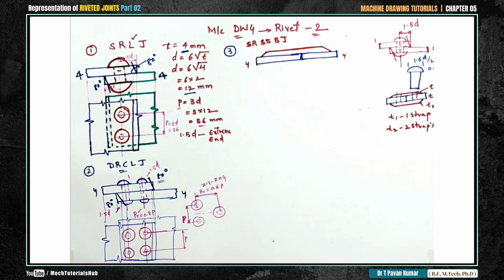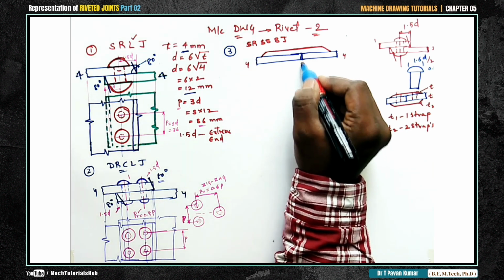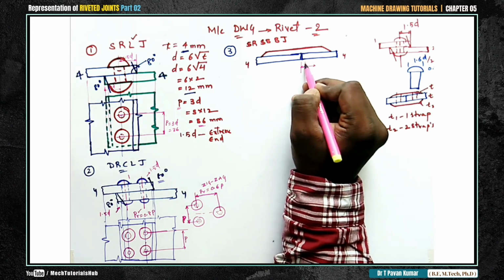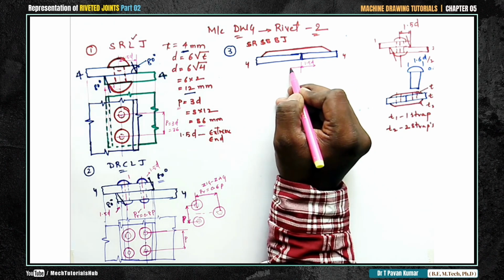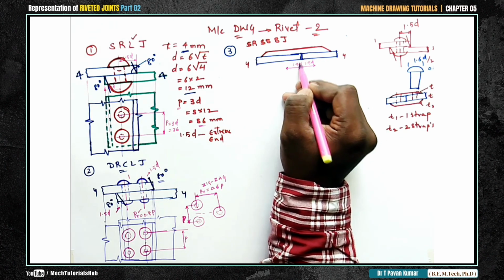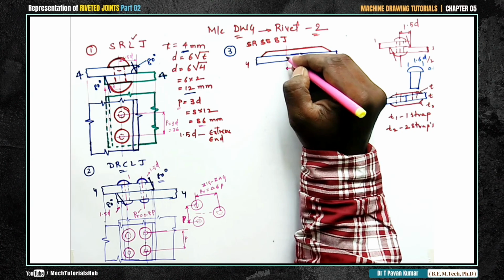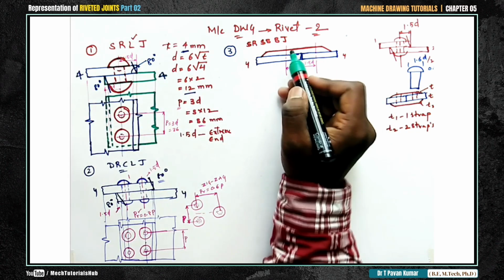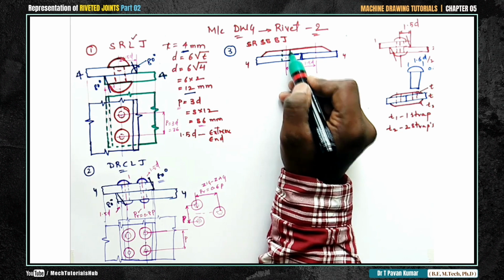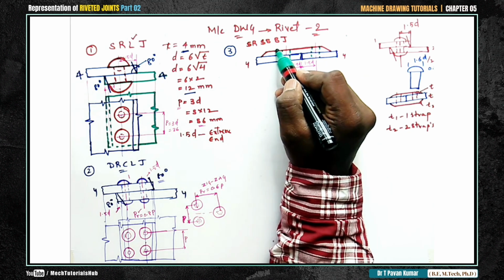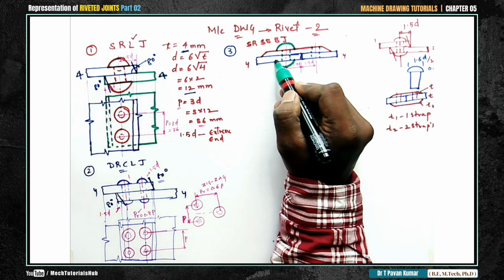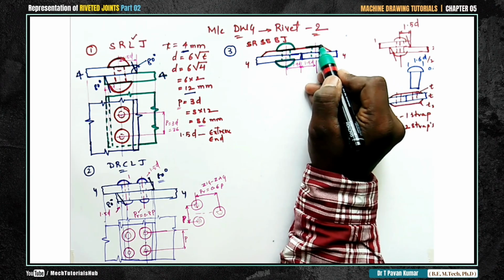Now everything will remain the same. From the center of the butt, wherever you made a butt, to the center of the rivet, this distance is 1.5 D. This distance will also remain the same, 1.5 D. Here you need to place your axis line. Now all other process is similar, the way we did for the lap joint. We will drill a hole of whatever diameter we calculated. Then we'll place a head of dimension 0.7 D by 1.6 D. I'll try to darken the required portion.